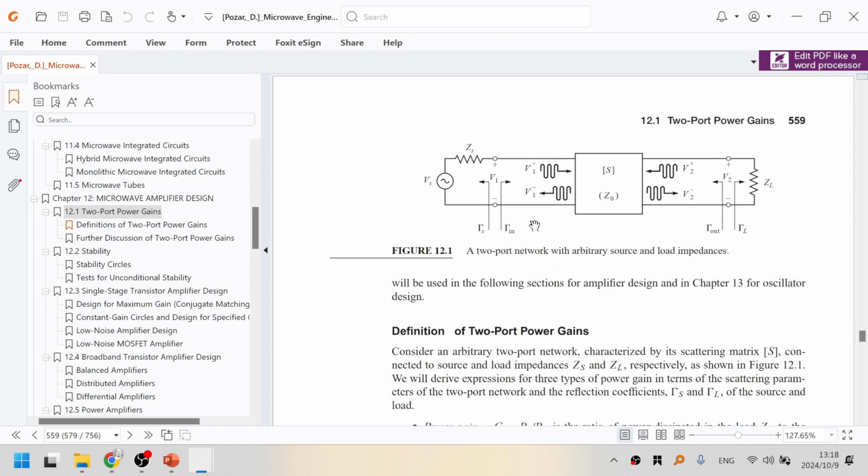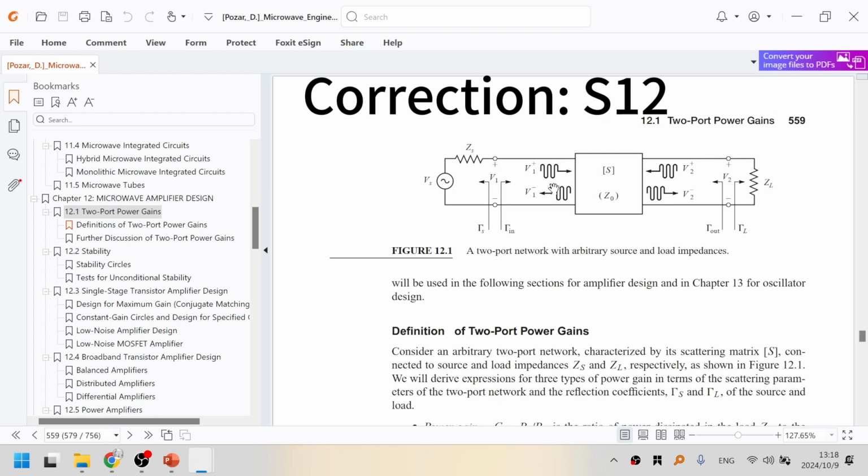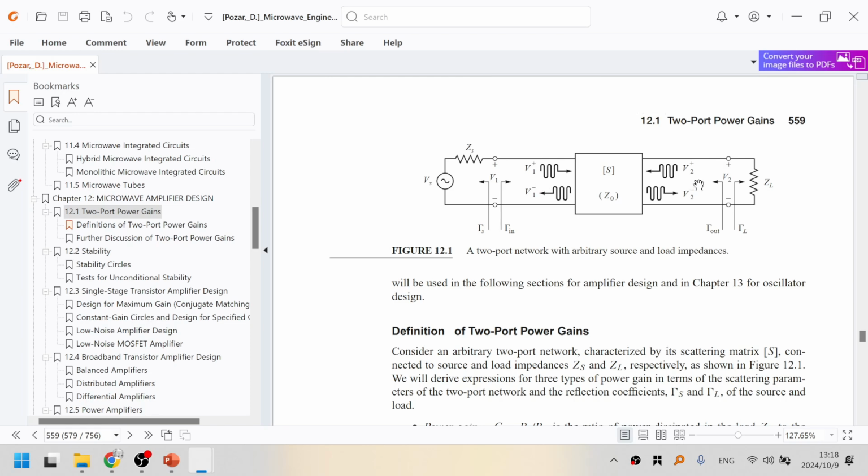The way we look at the amplifier in the microwave circuit is as a two-port network. The unique feature of this kind of amplifier is that it has a very high value of S21 but a low value of S12, so that most power is amplified from port 1 into port 2, and there is high isolation from port 2 to port 1. But because we are using real transistors, it is not ideal, and therefore S12, which means port 1 affected by port 2, is never zero.